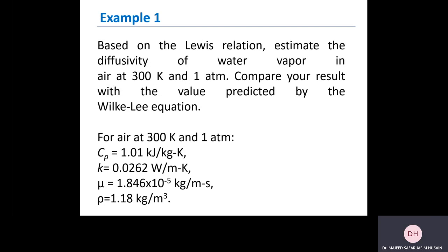After that, compare your result with the value predicted by the Wilke-Lee equation. I have given you the Wilke-Lee relationship. You have to go back, calculate the diffusivity for this case using the Wilke-Lee equation, and compare that value with the value you get from this Lewis relationship.